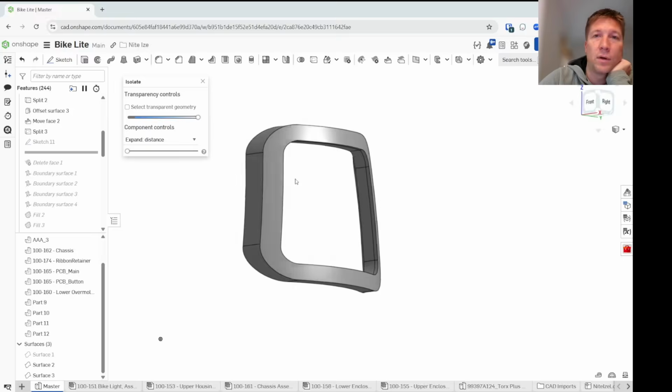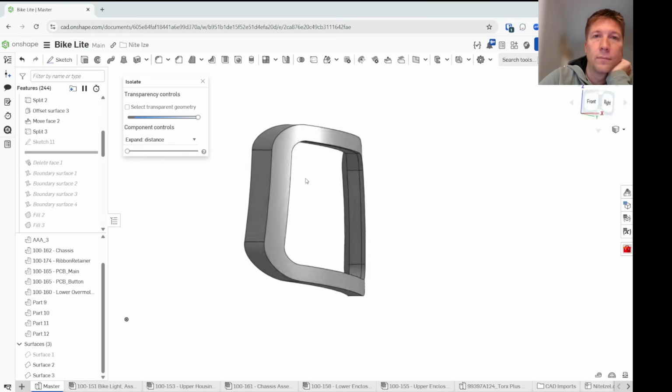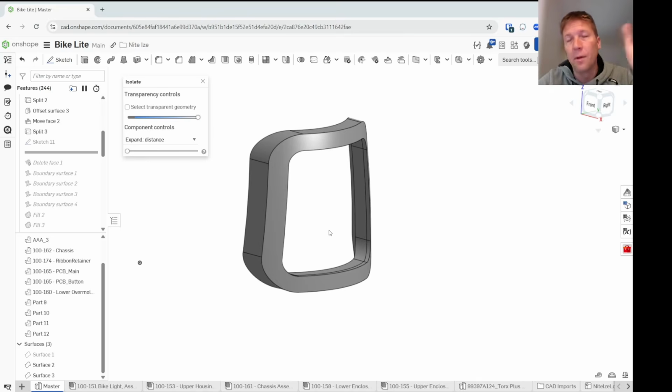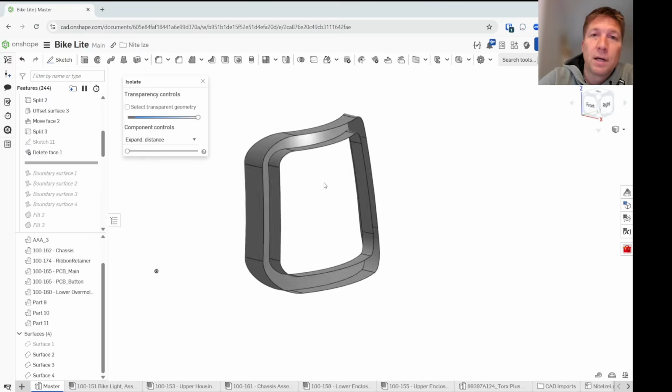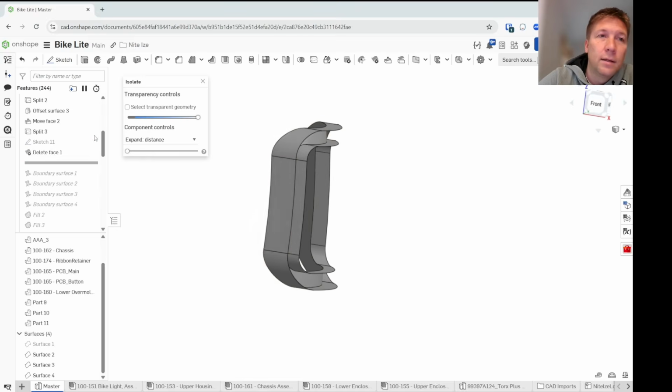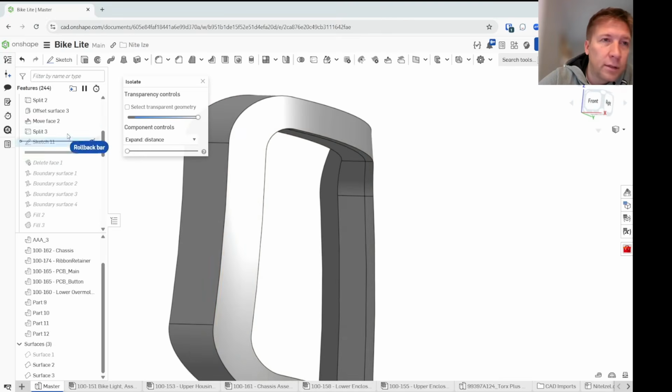So this used to be one of the bodies. If you remember, this came from the two tube surfaces that I cut out from the main body. And then I did a delete face on the front, so now I'm left with the surface body. And if you look closely, remember, I'll actually roll this back. So here was the solid.